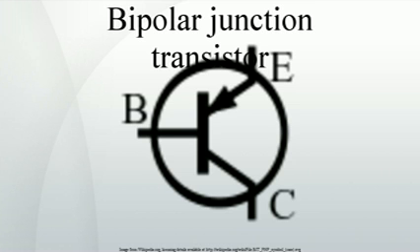H-parameter model. Another model commonly used to analyze BJT circuits is the H-parameter model, closely related to the hybrid pi model and the Y-parameter two-port, but using input current and output voltage as independent variables, rather than input and output voltages. This two-port network is particularly suited to BJTs as it lends itself easily to the analysis of circuit behavior, and may be used to develop further accurate models.